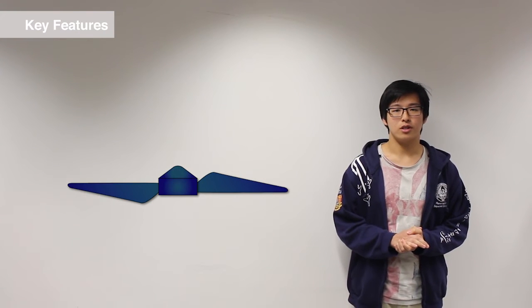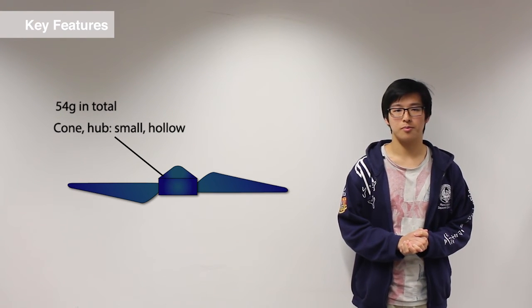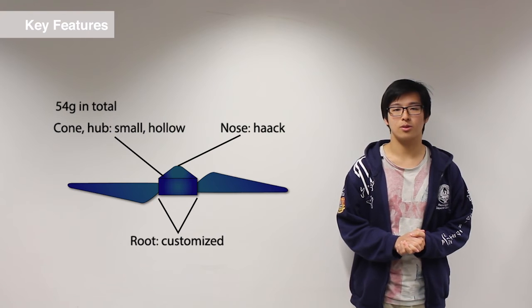Overall, the 3 key features of our design were: low mass of 54 grams thanks to the short hub and a small hollow nose cone, a customized root section to improve the turbine's aerodynamic properties, and finally, a Haack series nose cone used to minimize the drag.